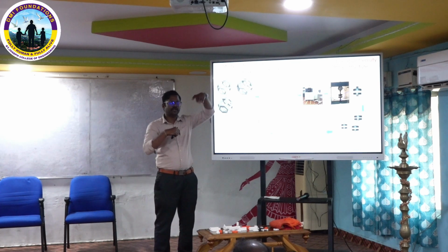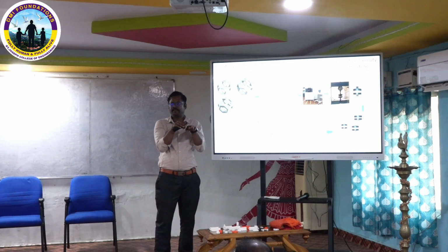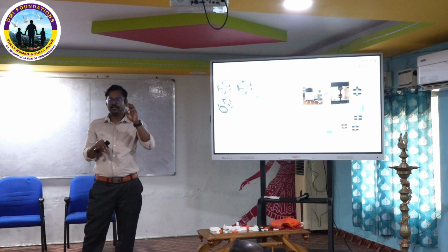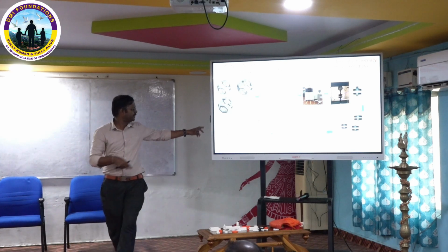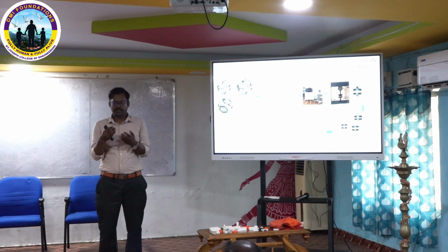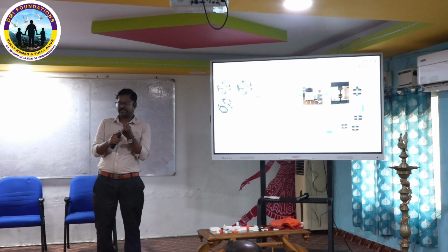Looking at the top view, this is my product cross section, and the laser will move like this. For each line there will be overlap. Overlap should be there, otherwise if the laser power is reduced, the energy density is low and there will be unsintered portions. So pores will be there, and that will affect the density and properties of the lattices.